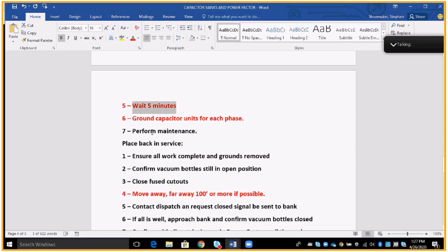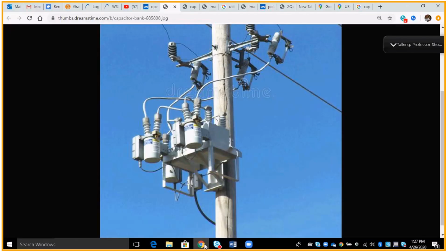All right, perform all the maintenance that you need. All right, well, it's just plain and simple. This low side riser was burned up. So I recut it, reinstalled one, put it in. This cell was bad. So I disconnected the leads, pulled it out, put one back in, reconnected it, whatever you need to do. This is a bad vacuum switch.